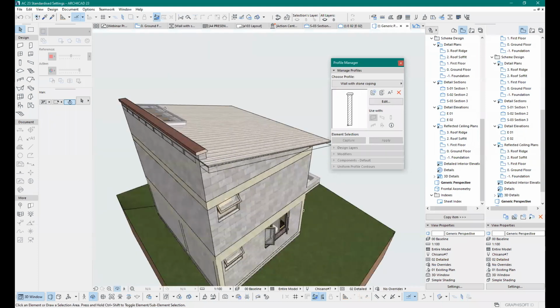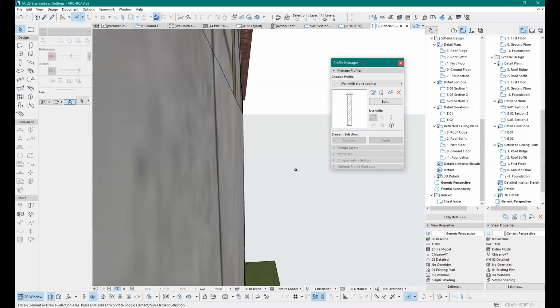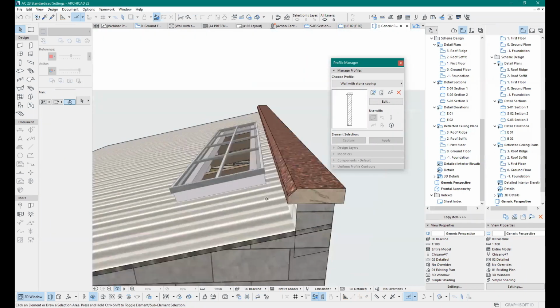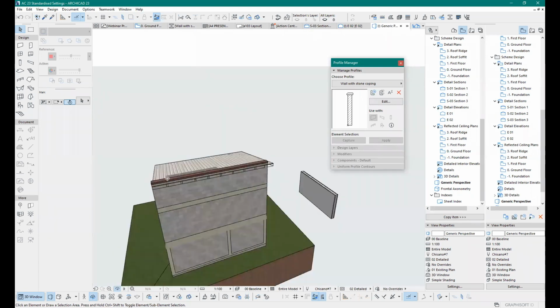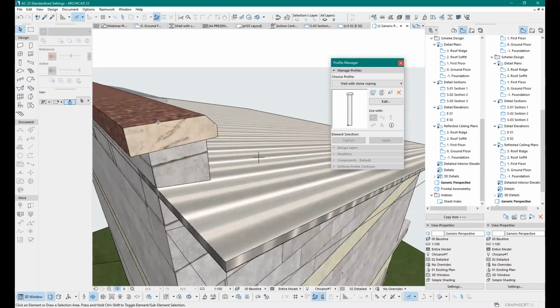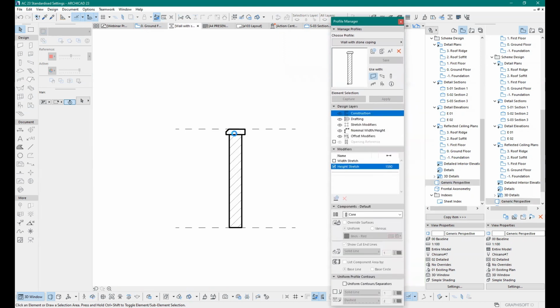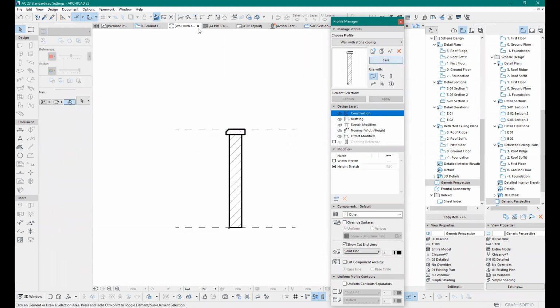Yeah, so just like that, I'm able to create a condition which I would have been unable had I been using the default ArchiCAD files. And this is due to the use of complex profile. But I see that something is not as it should be here. So this surface, I would have wanted it to look like the top. So let's edit again. So I'll select the top here, and let's remove override surfaces and see how it will behave.